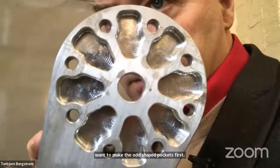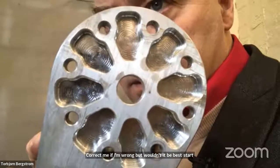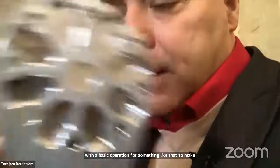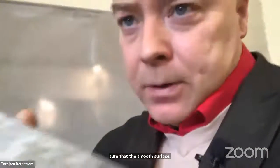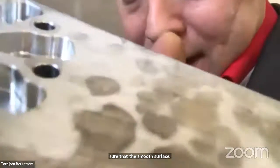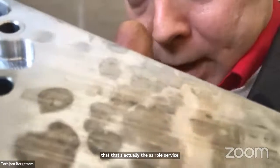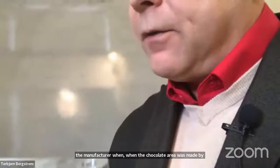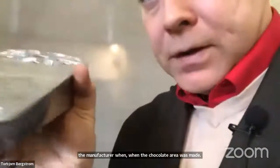Correct me if I'm wrong, but wouldn't it be best to start with a facing operation for something like that to make sure that's a smooth surface? I was going to say that as well. With this particular part, the customer didn't care. It's got fingerprints all over it, but you can see that that's actually the as-rolled surface from the manufacturer when the stock material was made. But yeah, you might start with a facing operation to get a nice smooth surface there.